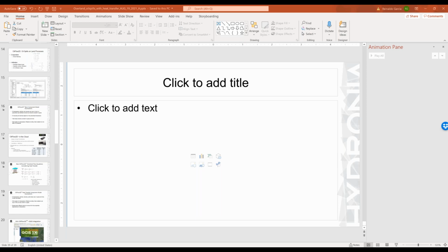And it highly depends on your surface. If it's a flat surface, it's one thing. If it's very mountainous terrain, it's a different thing. But the bottom line here is that you will need to do your own convergence analysis depending on the terrain that you have. But I don't think you need to go to 2 centimeters in order to get good results at all, at least from our experience.